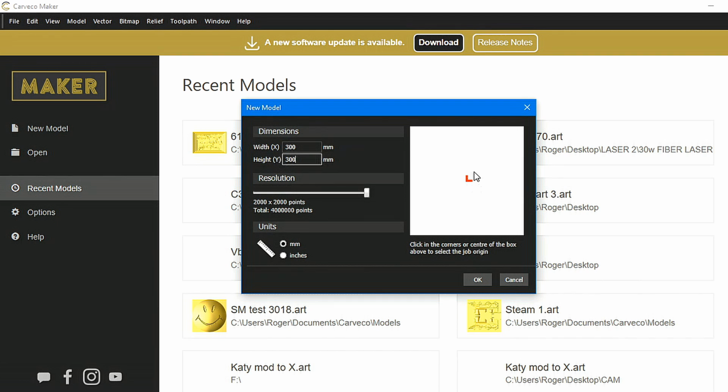and now this is the 00 or the G54 or the orientation start of the program. So you have a choice of putting it in 5 different areas: there, here, in any of the corners, or the center. This particular job, we're going to start down in this bottom left hand corner, which is fairly normal for a CNC router.